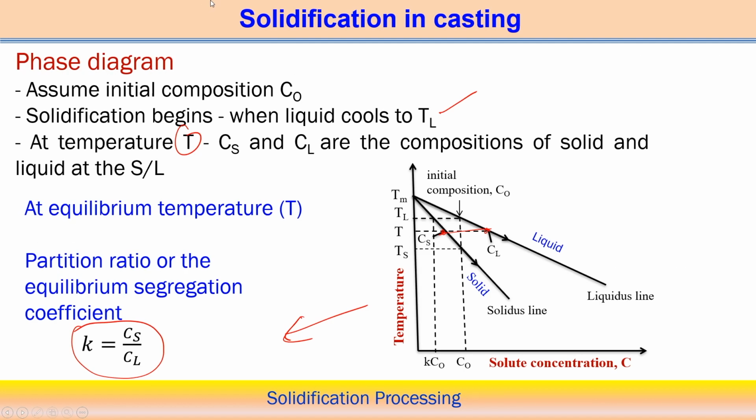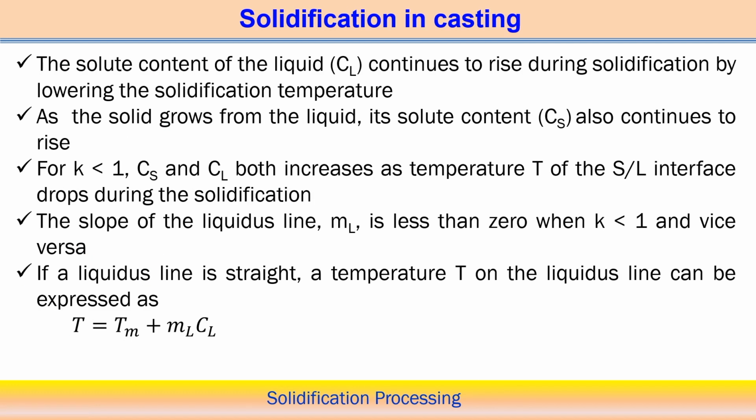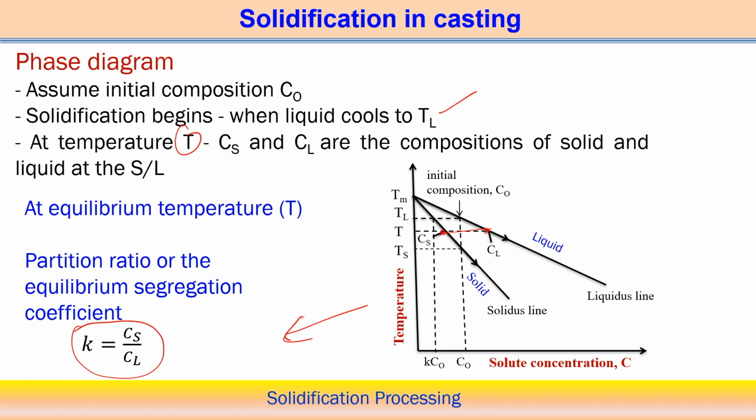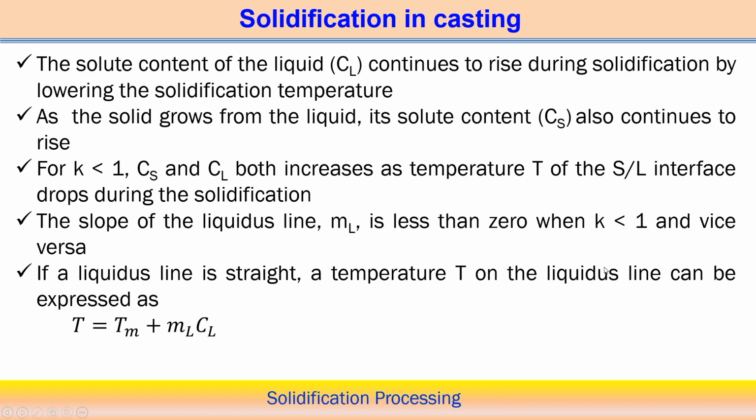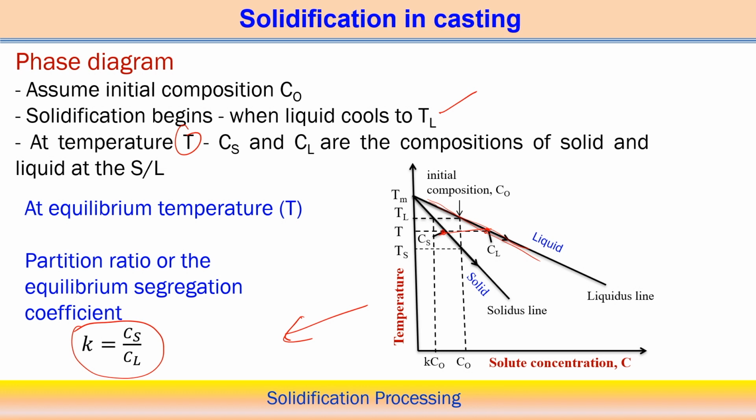Now, if we study this diagram, what conclusions can we form from it? First, the solute content of the liquid continues to rise during solidification. It is very obvious from this diagram that the solute concentration in the liquid phase is increasing, lowering the solidification temperature. At the same time, as the solid grows from the liquid, its solute content Cs also continues to rise.